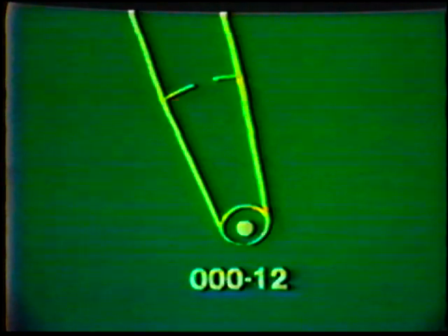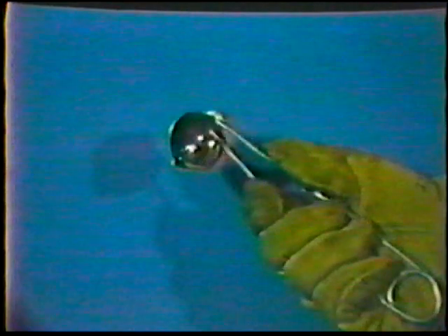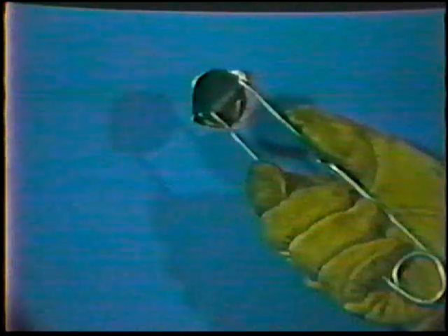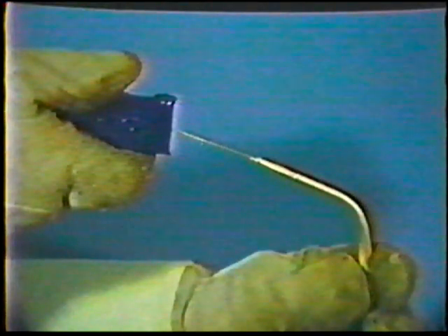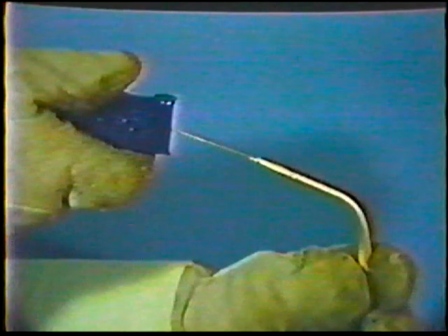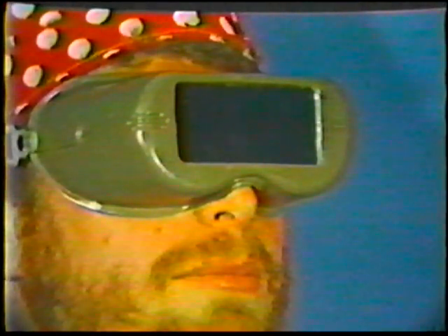Other equipment necessary for the process includes a friction or spark lighter, sometimes called a striker, to light the torch, a set of tip cleaners to periodically drill out the orifices, filter goggles suitable for eye protection, gloves to protect your hands from open flame or sparks, and protective clothing. Wear long sleeves so that your wrists and forearms are covered. Wear high-topped shoes, if possible, and cuffless trousers, especially when cutting, to avoid catching hot particles and sparks.